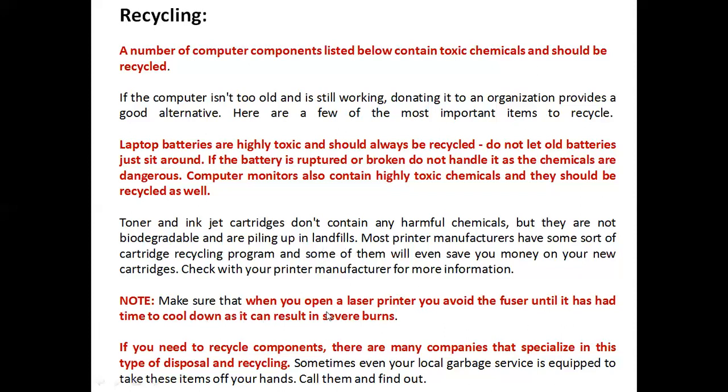Make sure that when you open a laser printer, you avoid the fuser until it has had time to cool down, as it can result in severe burn. Whenever you are working on your laser printer, first you should make sure it is cooled down. Then only you work with that. Otherwise, you can get burned.